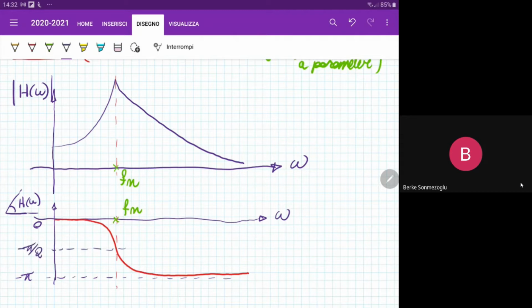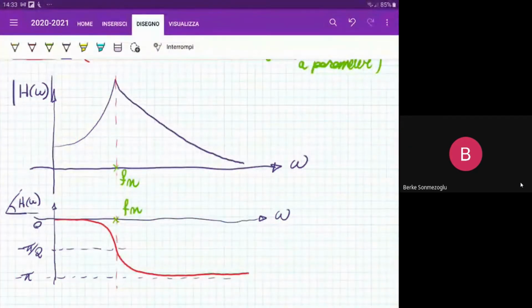I am referring here to the receptance, that is the relation between, for example, the output displacement and the input loading force. What does it mean that? Please be sure to have this picture very clear in mind, because it could happen that I will ask you to draw, during your final exam, a picture representing whatever frequency response function. And sometimes there are lots of big mistakes in representing this function.